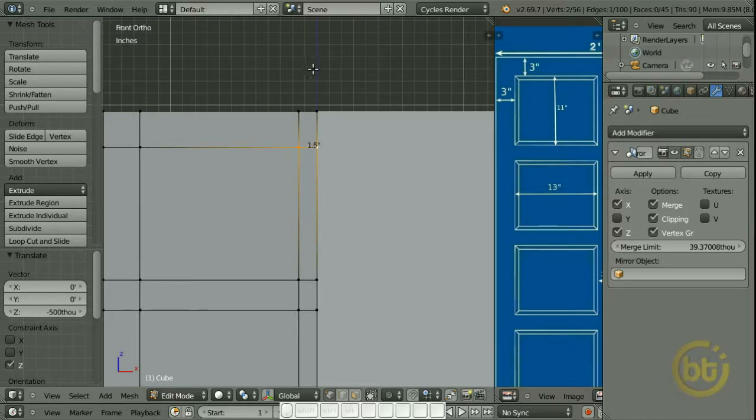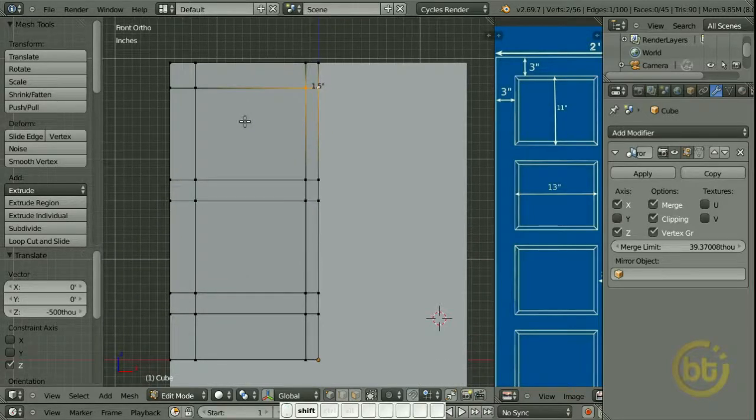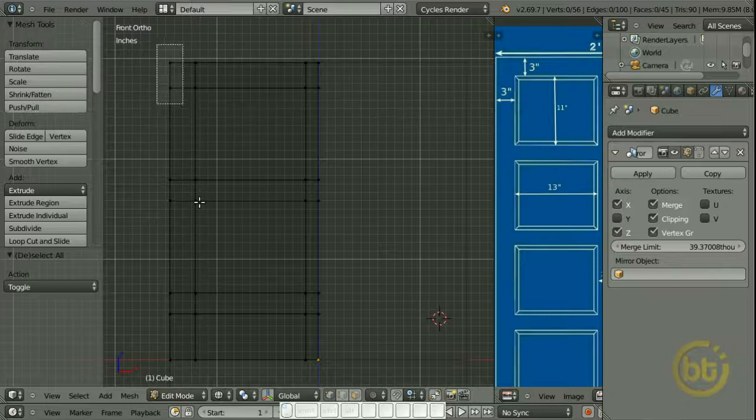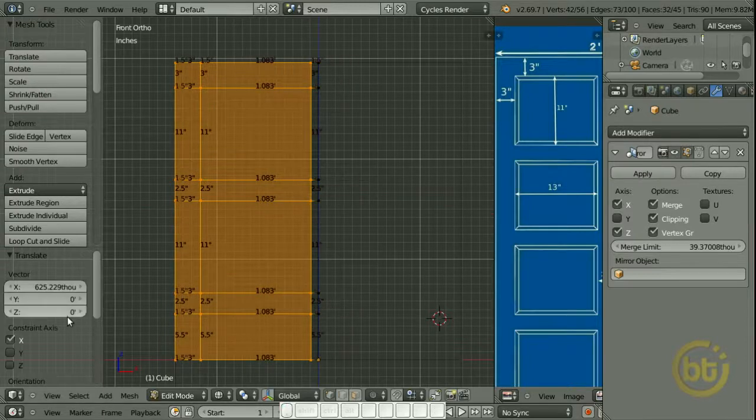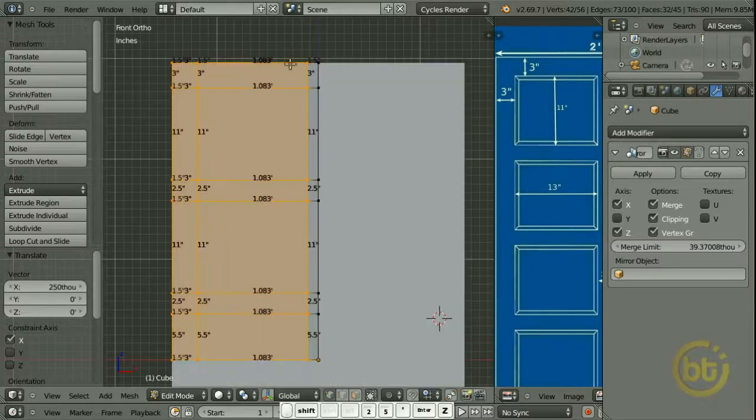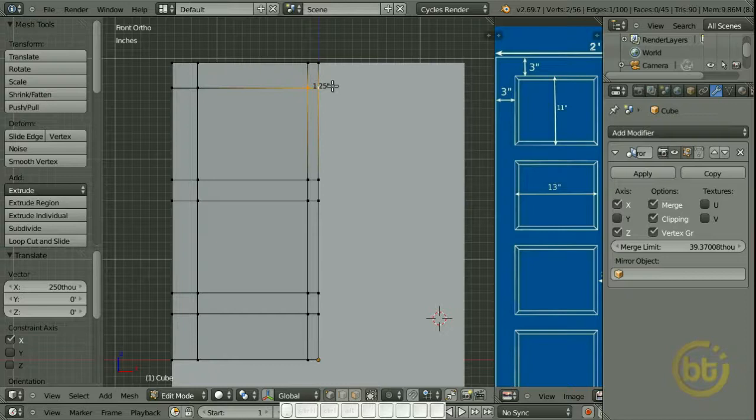But the middle rail and the cross rail are 2.5 inch length. For that we need to reduce 0.25. Go to the wireframe mode. If we reduce 0.25 inch, this side and that side also reduce 0.25, so totally we will reduce 0.5 inch. G, lock it to the x-axis. Just move this one like that and set this value to 0.25 inch. I'll check this value. Now it's just 1.25 and this side also we have 1.25. Totally we have 2.5 inch. Okay, now the door is in exact real world scale size.